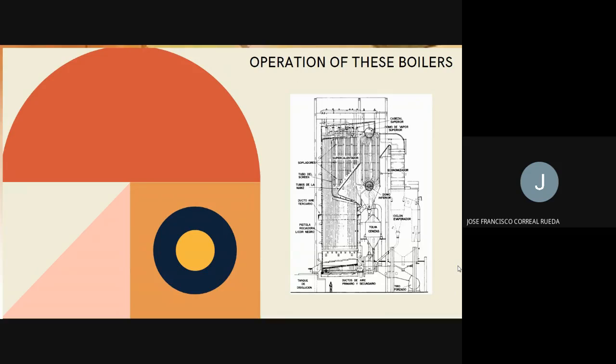The boiler is made of a cold side and a hot side, guaranteeing the natural circulation of water and producing the boiling of the water, which releases steam bubbles that are finally separated from the water in the steam dome. The gases at the outlet have low temperatures, but they have a residual thermal energy necessary to preheat the feed water that passes through the economizer before entering the steam dome. It's worth mentioning that water flows upstream.